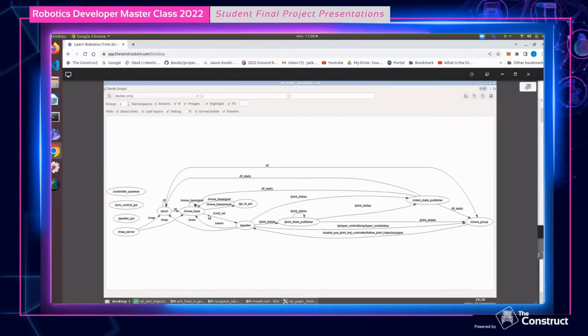And what else? Oh no, also for the gripper. MoveIt is responsible for the arm control, sorry, which is basically composed, like I said, of the two controllers: the joint trajectory controller for the arm joints, the scaled pose joint trajectory, I called it, and the gripper action controller.